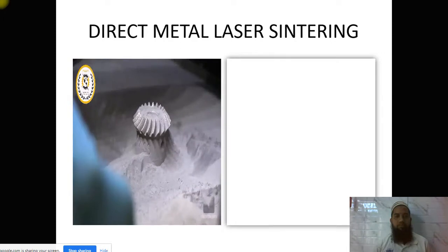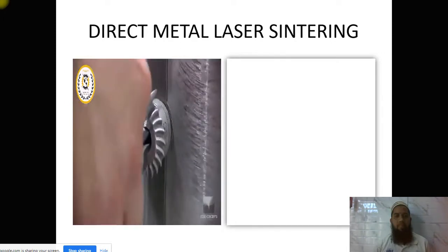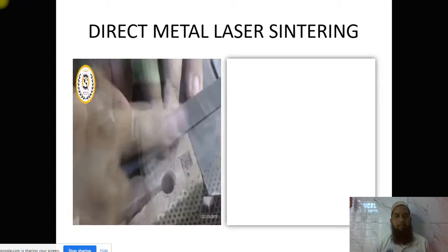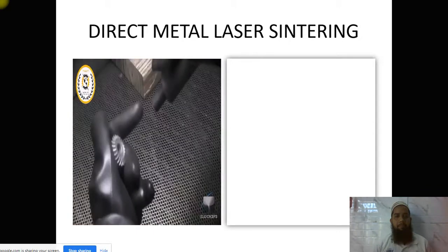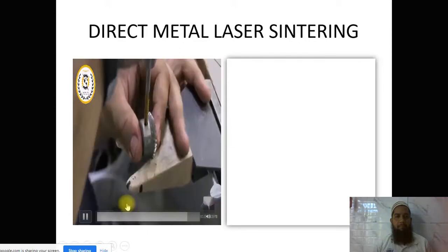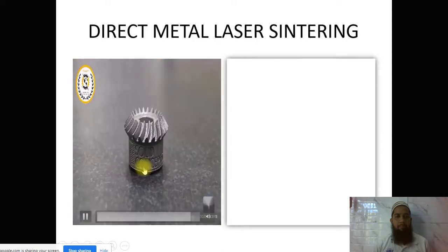The completed part is then removed from the base plate and treated with an age-hardening heat process to further harden the part. Any support structures are also removed at this time. With numerous surface treatment and hand polishing options available through service providers such as Solid Concepts, DMLS parts can be used in highly cosmetic applications. Typical uses for DMLS include tools and manufacturing aids, small integrated structures, dental components, surgical implants, and aerospace parts.